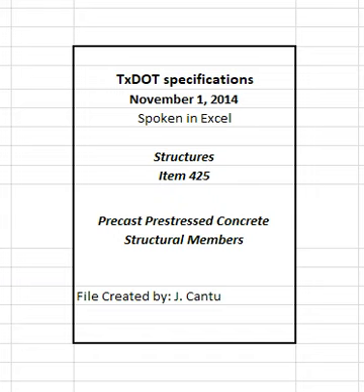Do not weld or torch cut near any prestressing steel, so that it is not exposed to weld spatter, direct heat, or short-circuit current flow. When prestressing steel for post-tensioning is installed in the ducts, any rust that forms during the first 14 days after installation will not be cause for rejection of the steel.